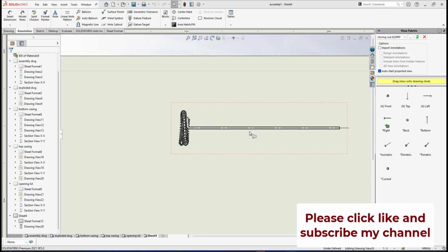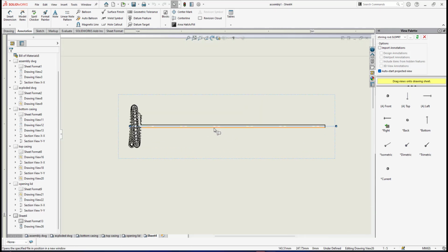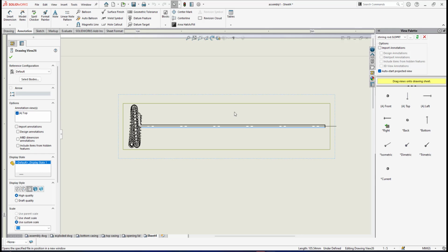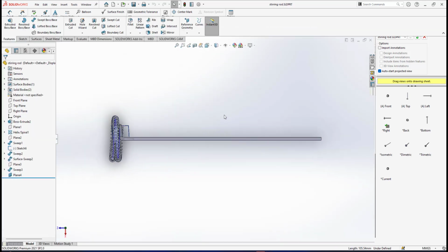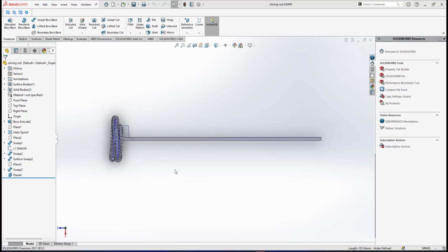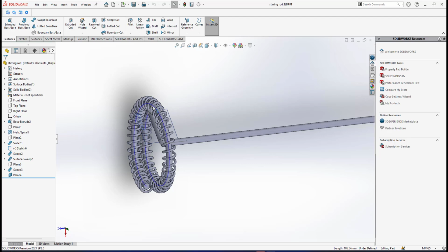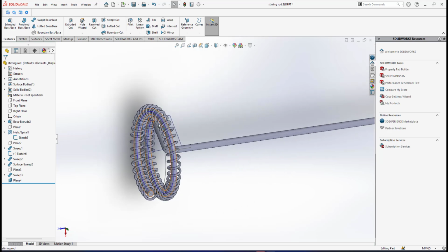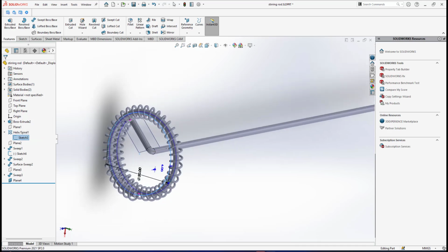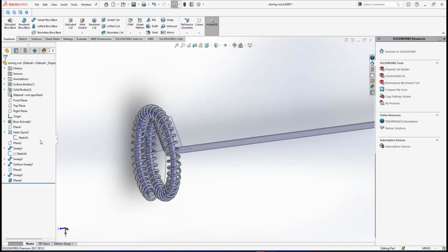Okay, another thing is that if I select this object here and open part in position, SolidWorks will open my steering rod part modeling file. Since I have this helical shape, I need to turn on that base circle that I used to create this helical curve, because I have a base circle of diameter 20 here. So it is on, and let me save my file.